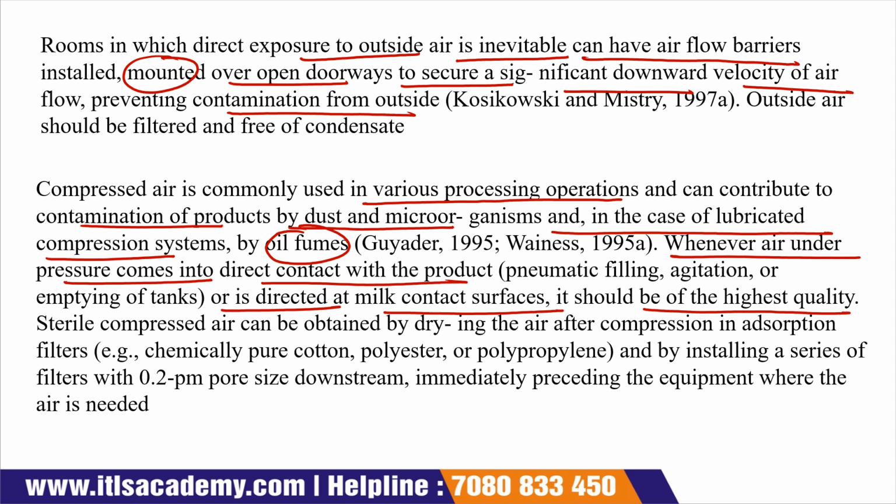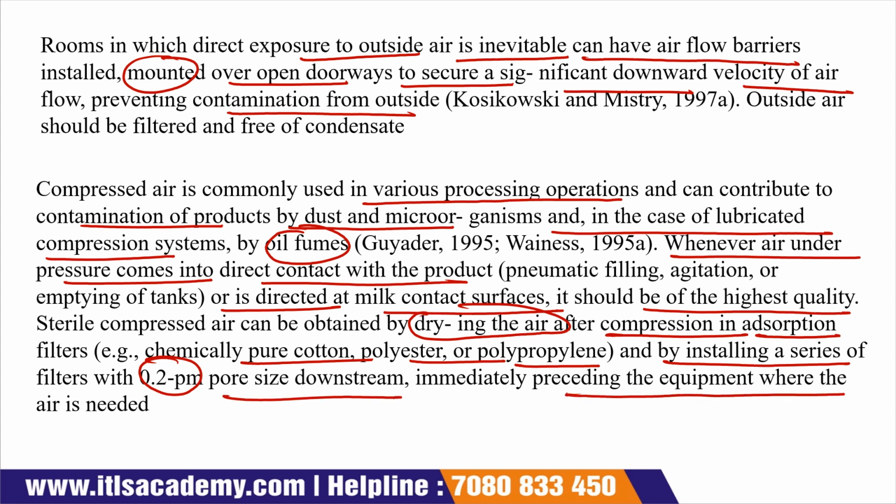Now, we can also use sterilized compressed air, which can be obtained by drying the air after compression in an adsorption filter, for example pure cotton, polyester or polypropylene, and by installing a series of filters with 0.2 µm pore size downstream, immediately preceding the equipment where the air is needed.